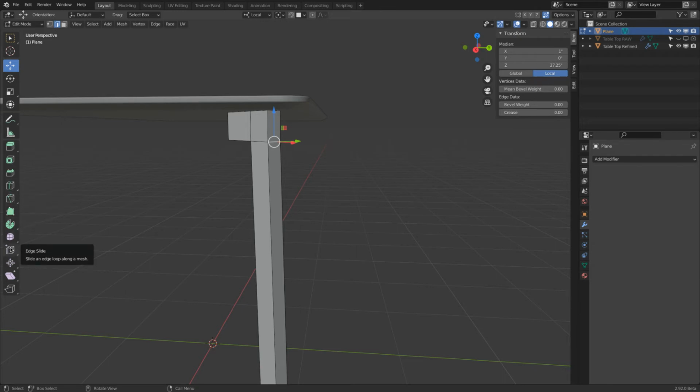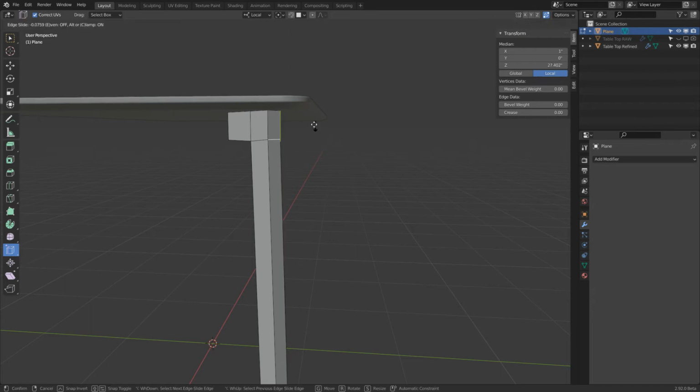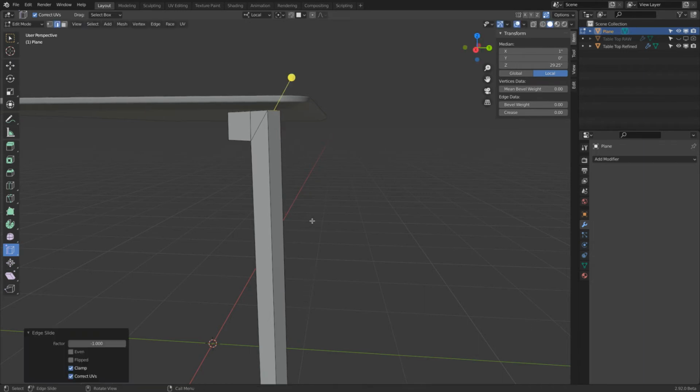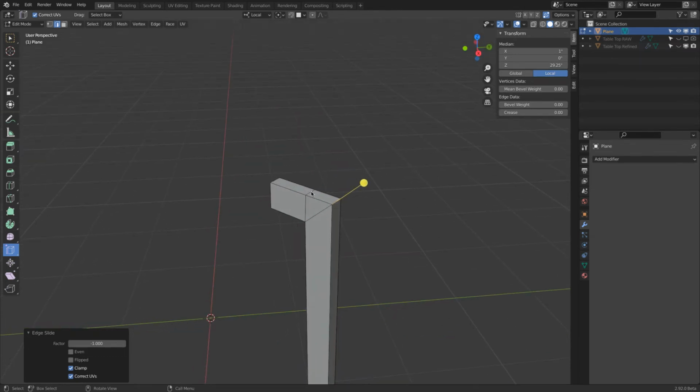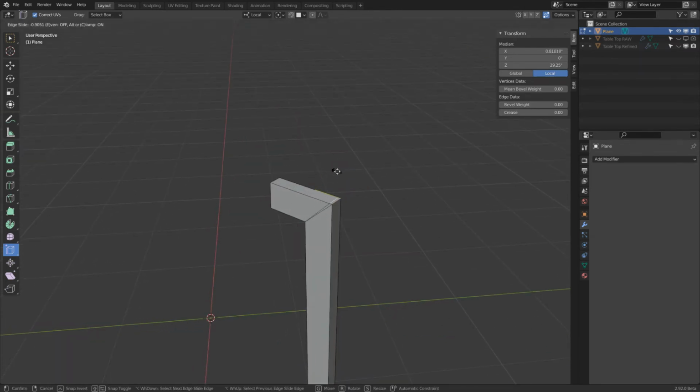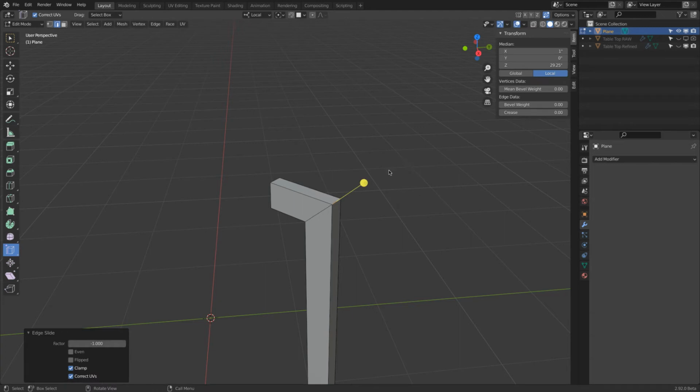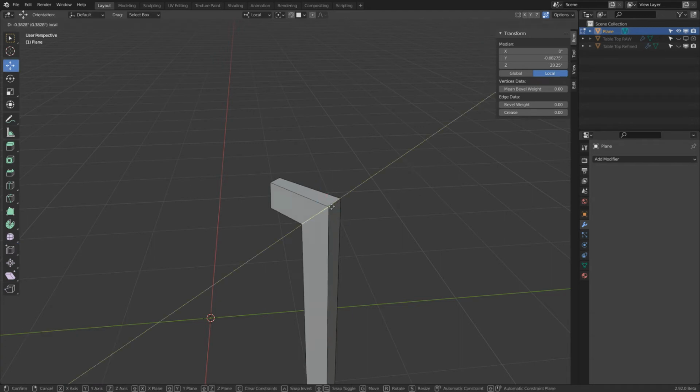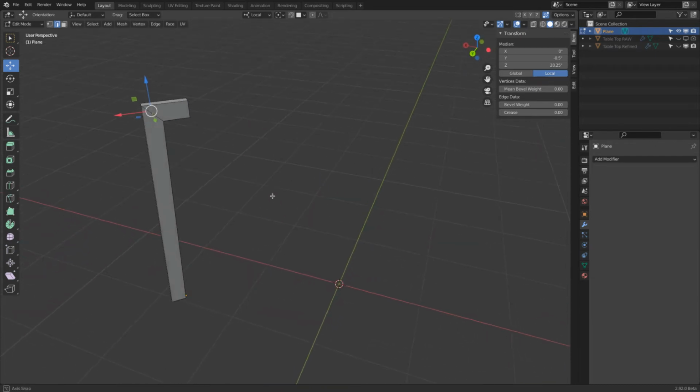There was actually, yeah, edge slide. Here's also the command for it. If you want to do it this way, instead of using GG, you can also use the command. There. We do this one more time actually here with this edge. Select it. Click the yellow button, go to there. Perfect. And also here we just only have a single edge. Nice.